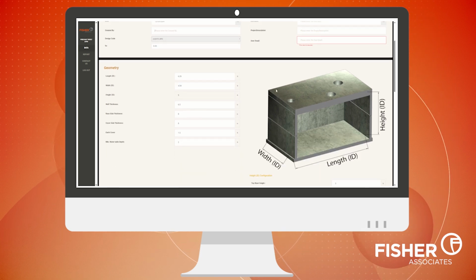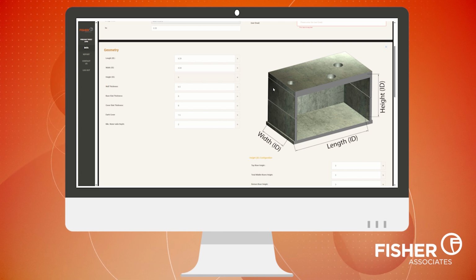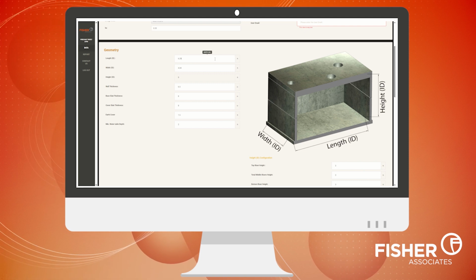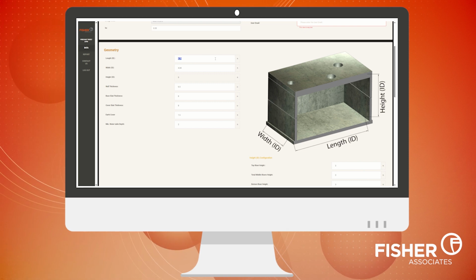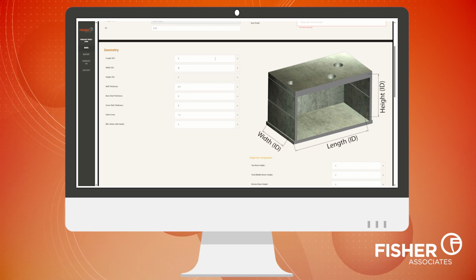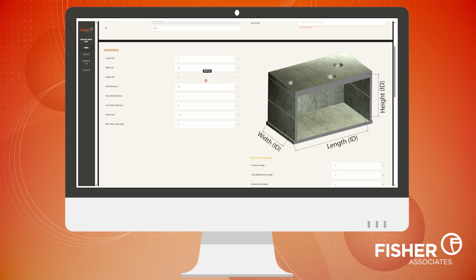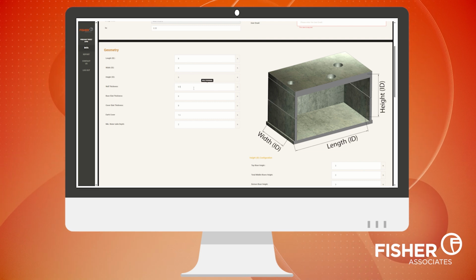In the geometry section, you'll need to input the internal dimensions: length, width, and height. Remember, the length refers to the longer dimension. For this example, we'll use 8 feet by 4 feet. The height field is currently inactive, as it depends on the configuration you'll select later, which we'll revisit shortly. Next, enter the wall thickness, which we'll set at 8 inches for this example. We'll also use 8 inches for both the base and top thicknesses.